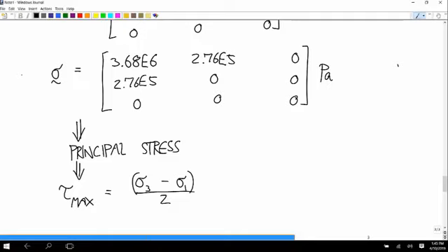Whereas with metals, this wouldn't be a very useful criterion for figuring out when it's going to break, because you could bend this beam over at 90 degrees and it would still hold. So then you have to use more complicated calculations to see whether you're worried about it breaking. Although this would still be useful for determining whether you're concerned that this steel bar is going to deform permanently, if you're trying to avoid that.